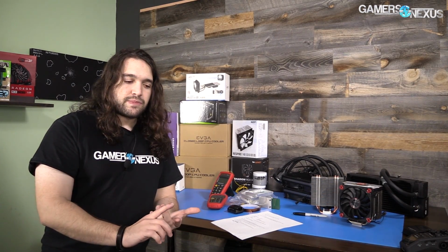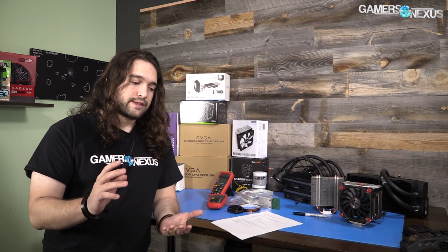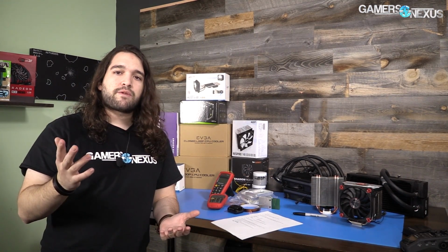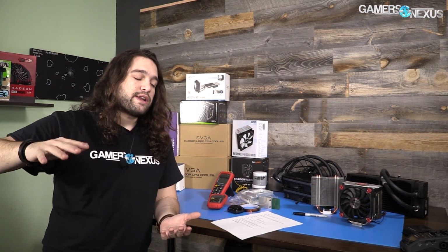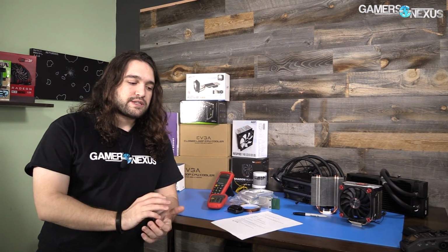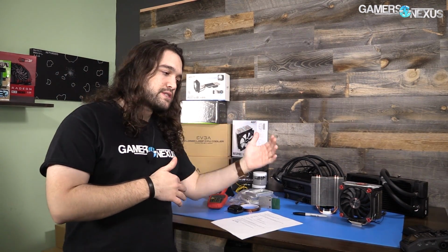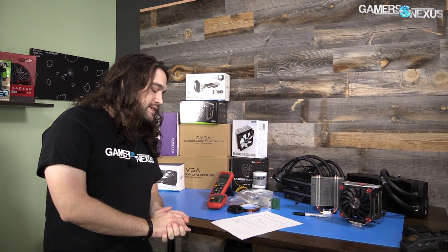For room ambient, just setting the thermostat is not good enough. So if you set your thermostat to say 20 Celsius, which is about what ours is, there's still going to be fluctuations, and some of it could be from a vent in the ceiling. If a vent is directly over a test bench one day and you move it and it's not the next day, that actually does have a big impact. And two, ambient fluctuates, of course, because the thing's going to toggle on and off throughout the day, whether it's heat or forced air or AC or whatever, that impacts things.